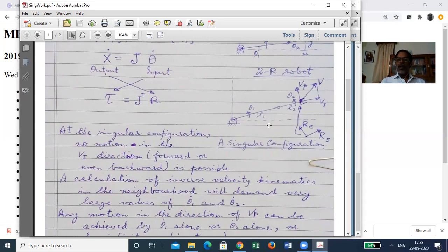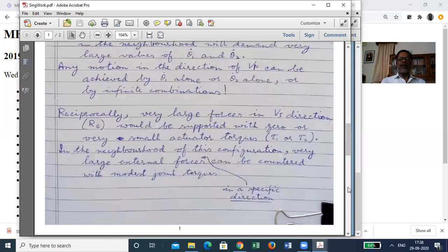Now here also you will find that coming towards the origin is impossible, which you can directly appreciate, because it is not in the workspace of the robot. But from here, even going the other way will be impossible. The way from this point, from this configuration, even coming inward was impossible at this configuration. Okay. Now we come to the issue of workspace.